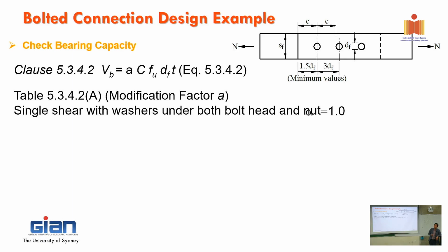But in saying that, they can only fasten the edge from the end of the material. So I think there's some confusion on that because of the difference between the center of the bolt and the center of the hole, right? I talked to Professor Hancock already, and he said yes, there's some confusion there. But as an engineer, you just choose the worst one to design for.